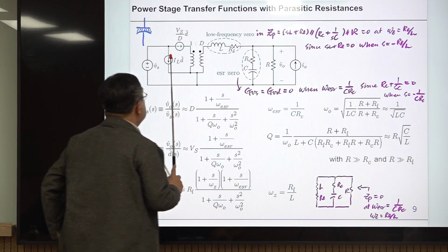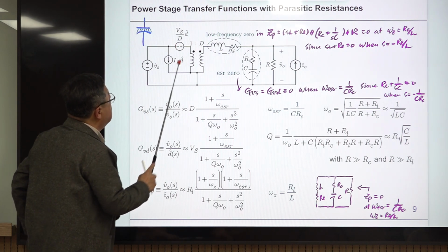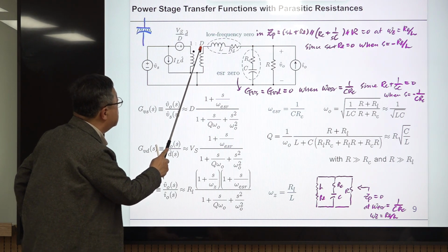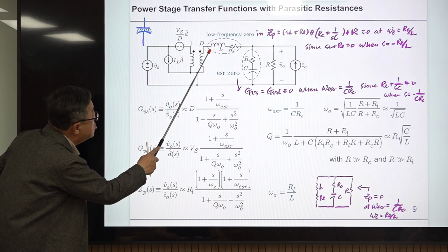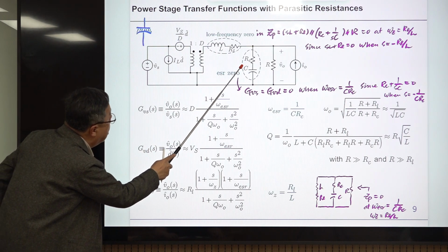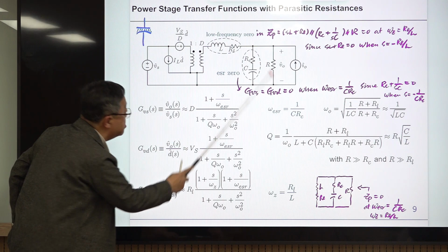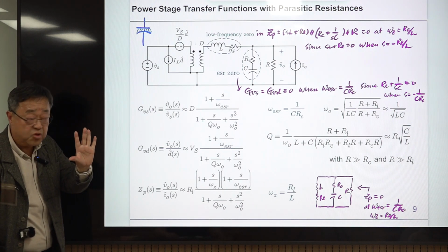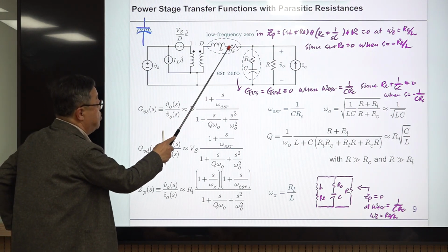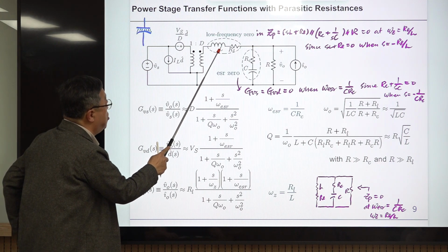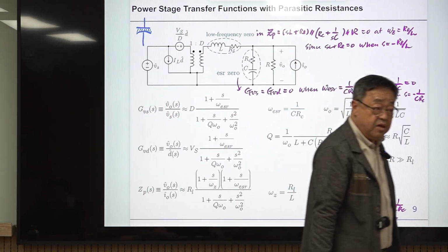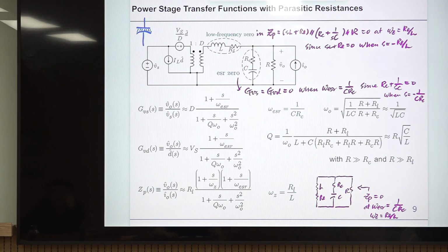So this is open. This showed it. And it is an ideal transformer. Then it is multiplied by this. So it appears here. And in this one, you have R, C, L, C, R. This one is what? A second order low pass filter. You know this, okay? Forget about this small resistance. Then you have a combination of the L, C, R, which is what? Low pass filter. You learned this many times, okay? So there is a low pass filter embedded in the small signal model.